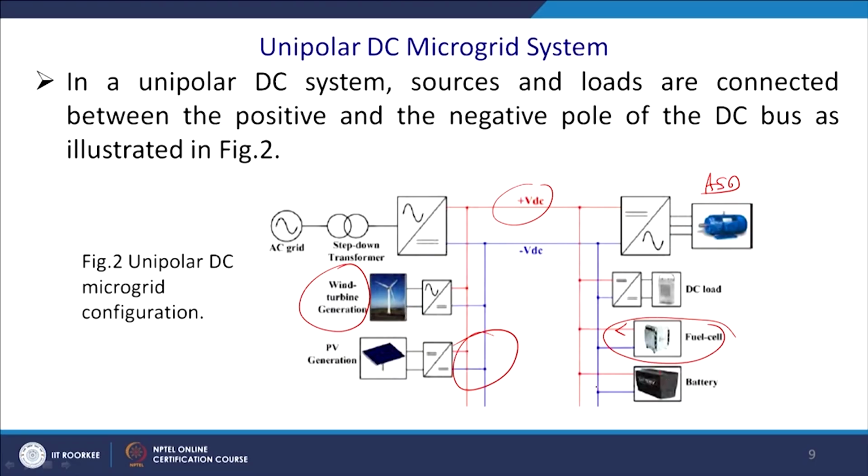Generally the battery will be interfaced by a DC to DC conversion, bipolar in nature. If you strictly maintain the battery voltage at 48 volt, then maybe a mechanical switch can operate.